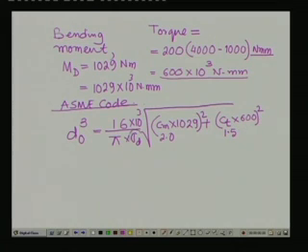What is the value of sigma design? This sigma design we can consider as 40 megapascal. Why? Because the ASME code suggests that it can be 56 MPa for shafts without keyways, and 40 MPa if it has a keyway. Of course, the pulleys and pinions will be attached with keyways. So, we consider this to be the value for the material property.